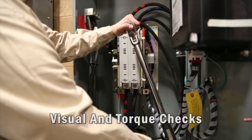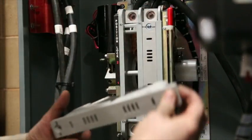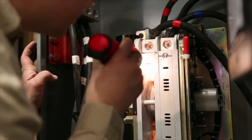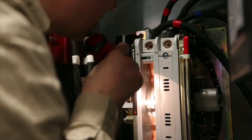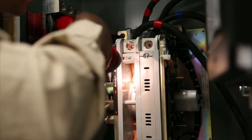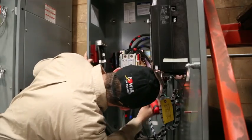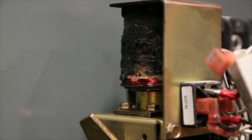Check the connections and torque tightness of normal, emergency, and load connections. Check the condition of air insulators. Check the condition of main contacts. Check the main power, mechanical operation, and integrity of the ATS switching mechanisms. Check the condition of auxiliary contacts. Check for evidence of arcing, hot spots, or other damage to the ATS.